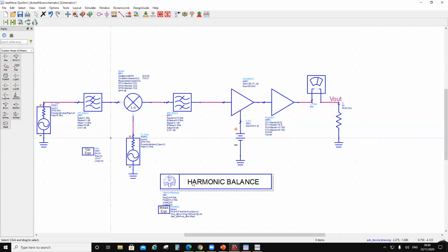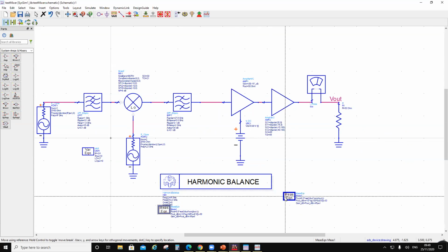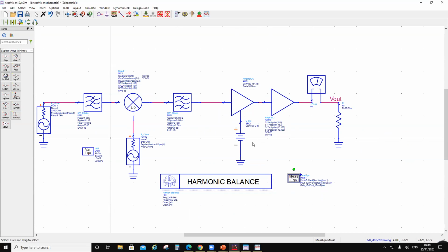So now this chain makes sense in terms of gain, in terms of compression, in terms of power delivered. Okay, so now what we are doing is we have a chain here. Now we want to analyze this chain. Now what is going to be restricting you from delivering so much power is the compression on this guy and the compression on this guy. Okay, because there is no other place where there is compression, right? So it's this one or this one, right? So usually this is the problem. Okay, why is this a problem?